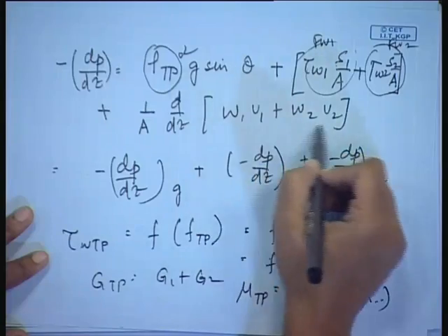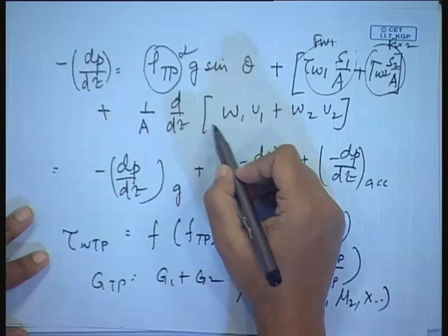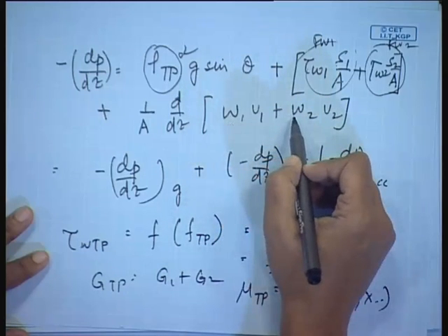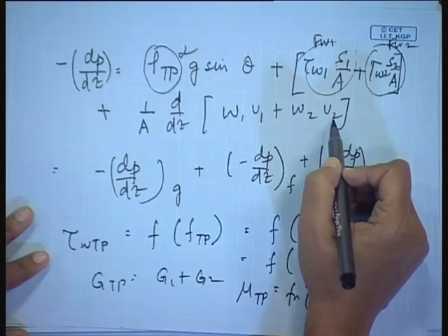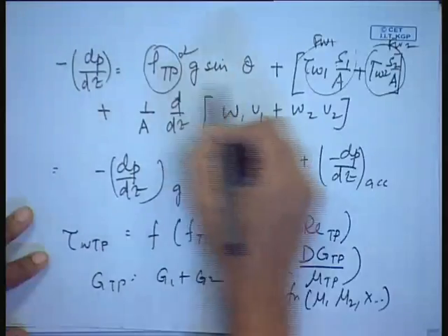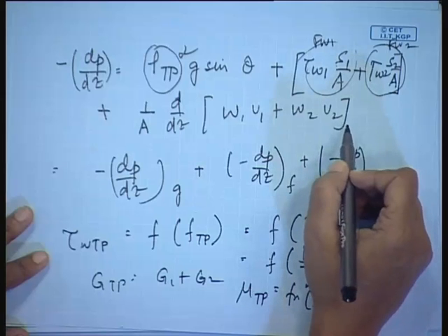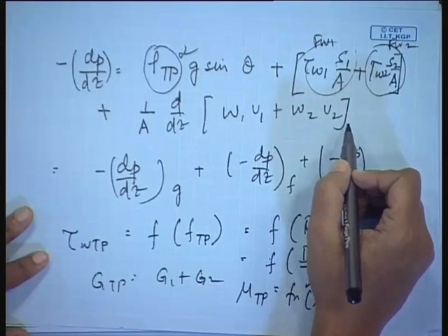In this particular case, alpha is a variable. It varies with x, it varies with other physical properties, and we have to devise ways of finding out alpha as well. Okay? And the second thing is, this is the same thing as in homogeneous flow theory. What we found, that W1, W2 they are input parameters, but U1, U2 they are not input parameters, they are in situ velocities. They have to be expressed in terms of certain input parameters. Only after that we can write down this particular equation in terms of known measurable properties.